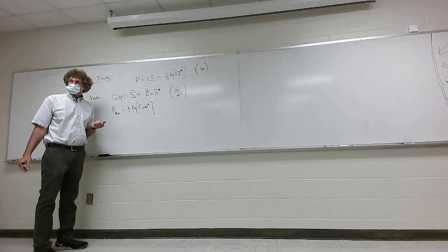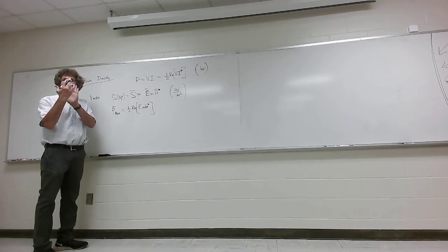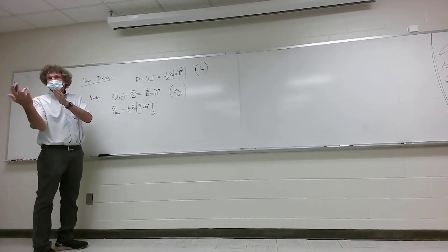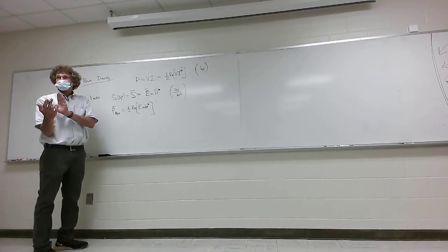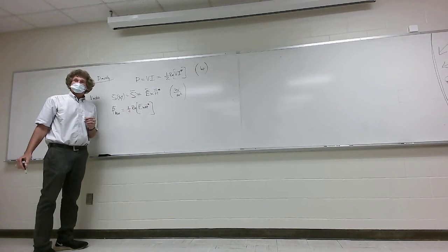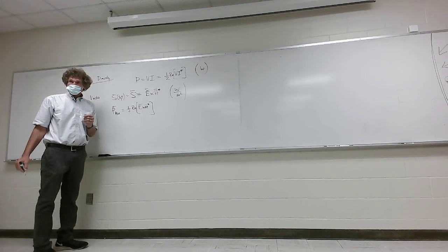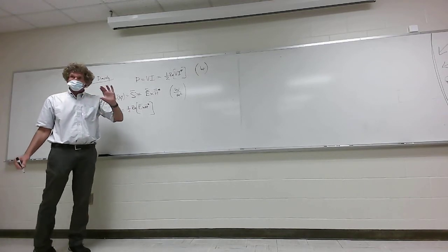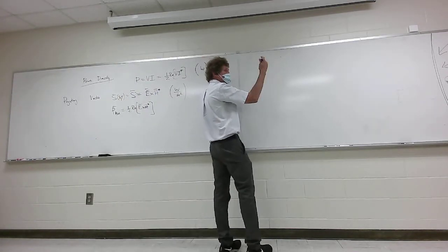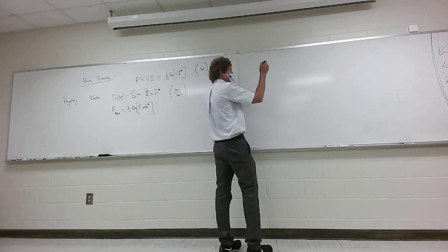Now the reason we use the average power density is that it gives you the average power that's flowing. So it's likened to, you know, RMS voltage kind of deal, all right? I mean, it's telling you something, not about the peak, but about the average, and that's the important thing. And this is assuming a sinusoidal variation too, by the way. It can't be just on, off, on, off. It's got to be sinusoidal or cosinusoidal. So when we talk in generalities about this, just listen to me now.